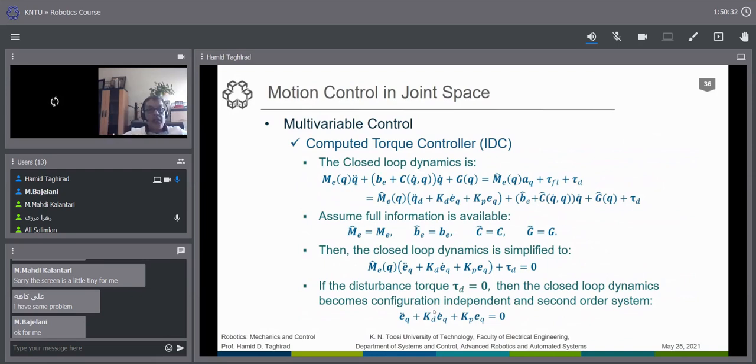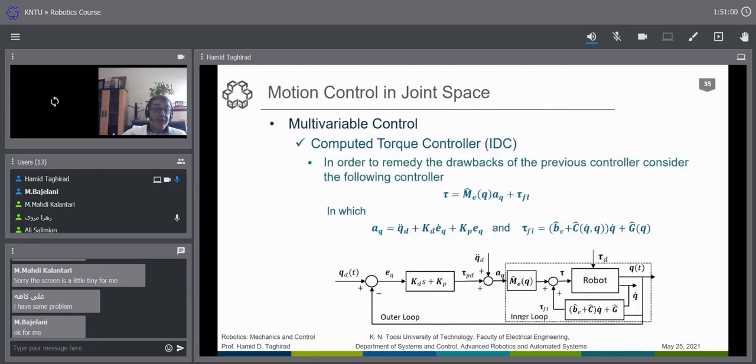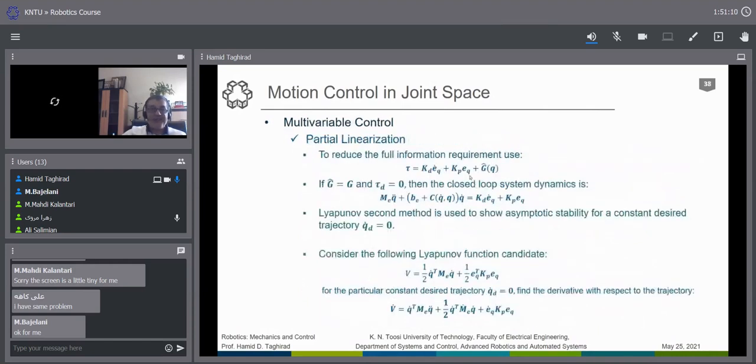We go with the zeta equal to 0.707, and then just tune in a simulation. You put this controller in the simulation, change the gain and see the response, the same way that you tune any controller. It is harder to tune the controller when you are using partial feedback linearization rather than full feedback linearization. Of course, if you have full knowledge of the system, the controller tuning becomes much simpler. But here you are using a much simpler controller. The controller is almost linear. The only term that you are adding is a gravity term, and the gravity is compensated by the controller.